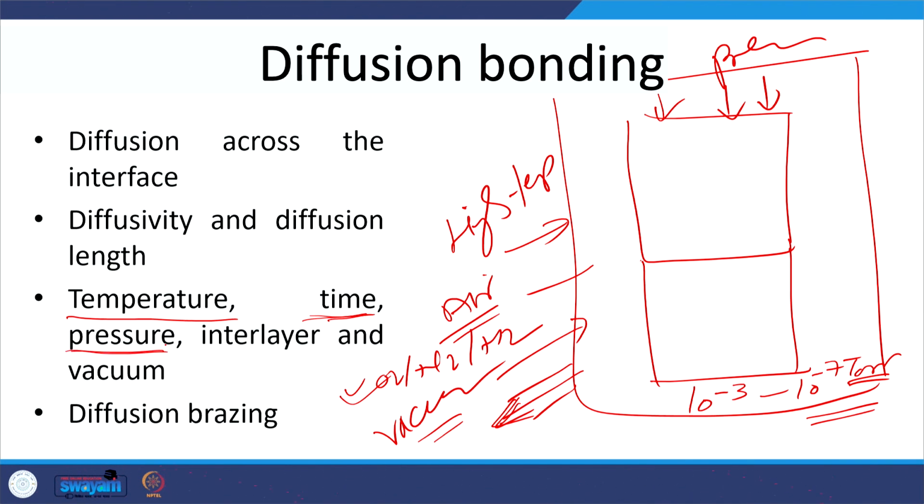If we apply lesser pressure, then the collapsing of the peaks and valleys at the interface will be limited, and metallic bonding will be limited in the initial stages. Later on, if we increase the pressure, the metal to metal bond improves due to the increased collapsing of the peaks and valleys, increased localized surface layer deformation, and increased creep behavior of the near surface layers.